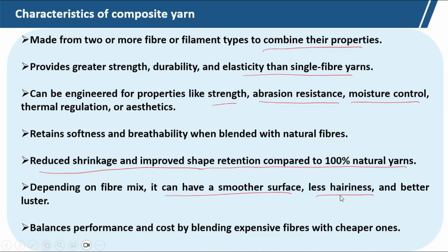Balanced performance and cost by blending expensive fiber with cheaper one. So, we can use the cheaper fiber at the core, hiding the negative characteristics, and put the expensive fiber at the sheath, with the lower proportion.